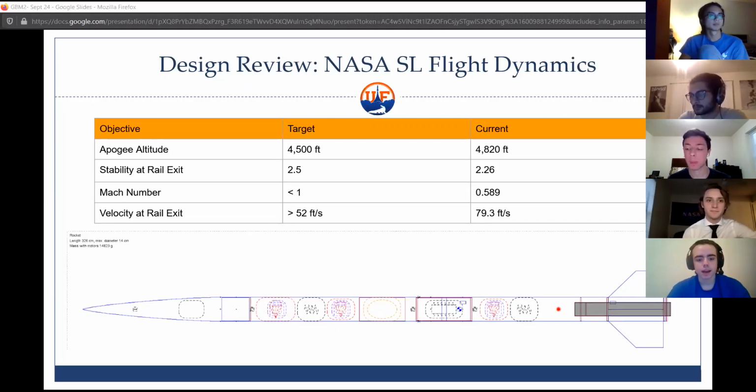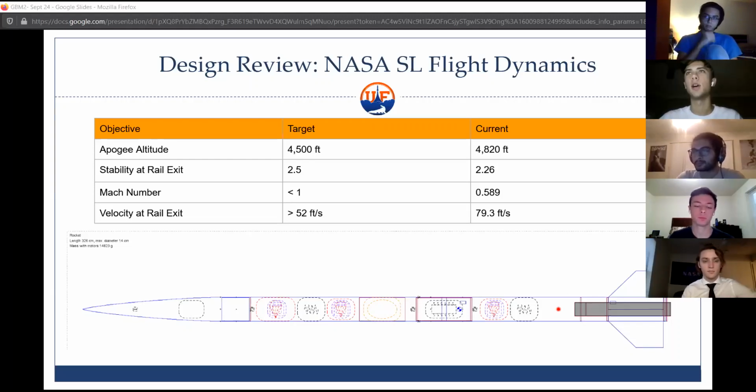So, yeah. How long is the payload? Because unless you do a really deep sand on it and it's kind of loose in there, you're going to have a lot of issues with getting it to eject, as well as the parachutes. I know right now, with the legs folded up, it's about 9 inches tall. I have a little extra space because I accounted for bigger batteries and more space in the middle compartment, so it could probably become 8 inches. But that's about as small as I can make the payload.